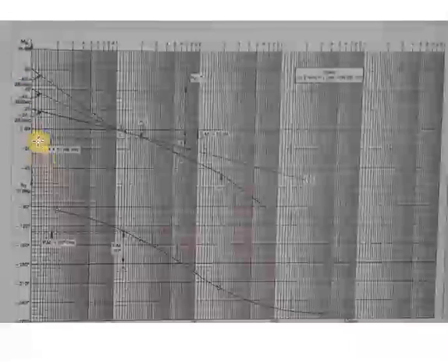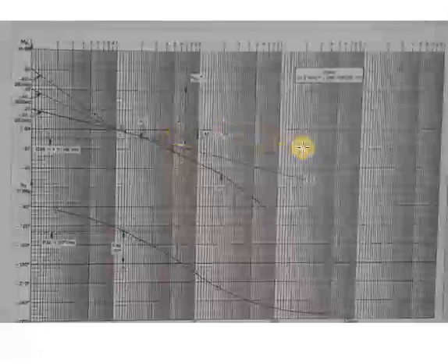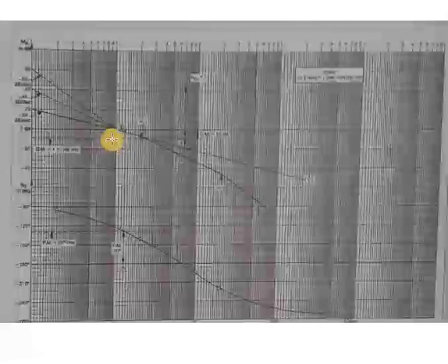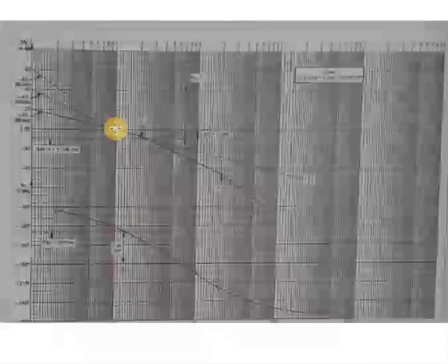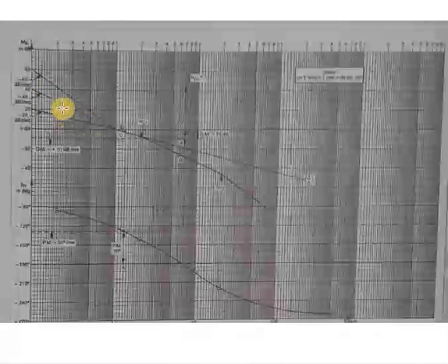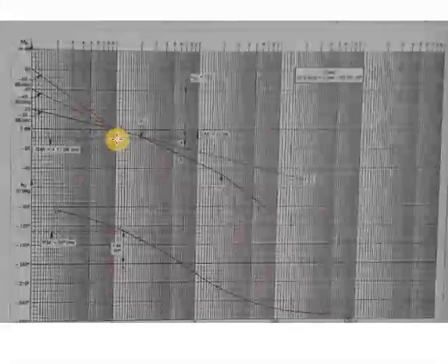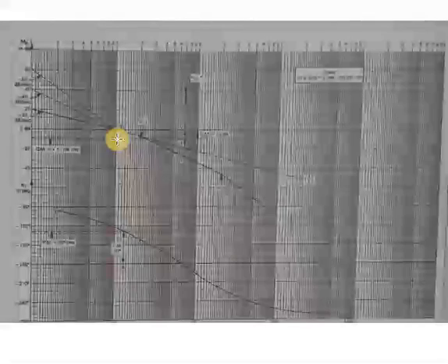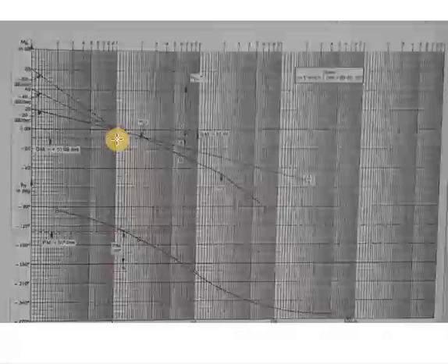So here, the first step is to draw a line at 0 dB and mark a point at omega equal to 1. Then draw these lines: minus 20, minus 40 and minus 60 are the cumulative slopes, and we have the break frequencies as 2 and 20.